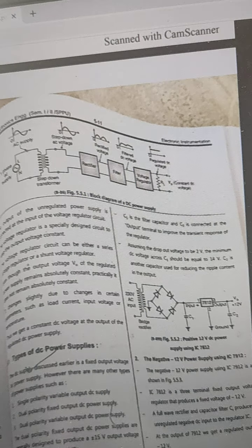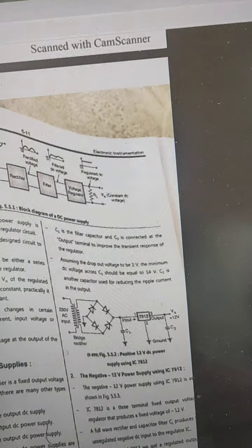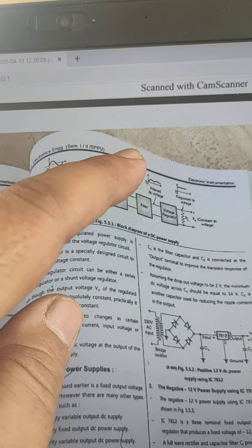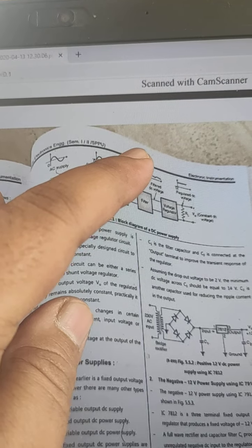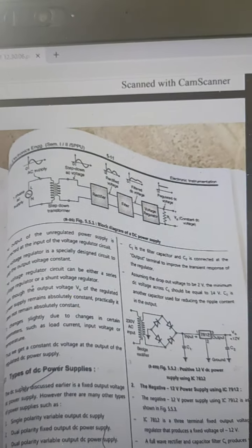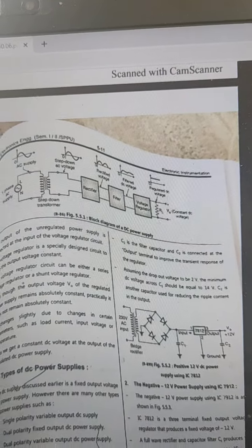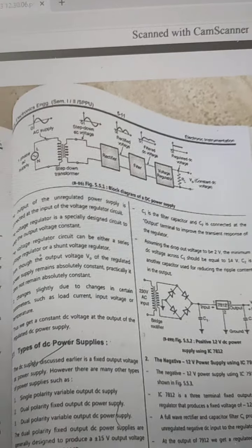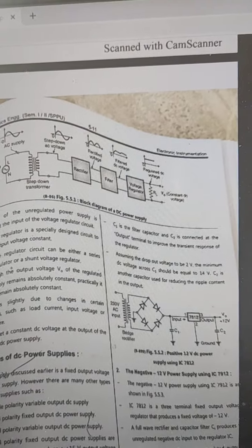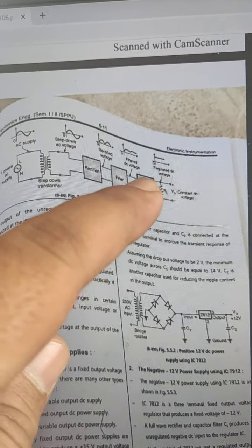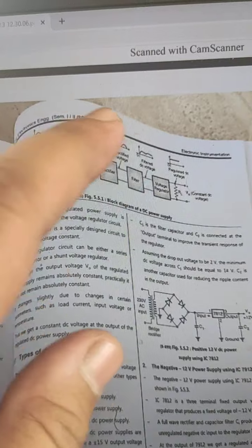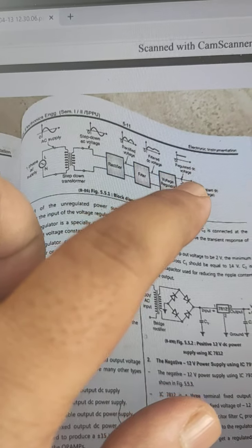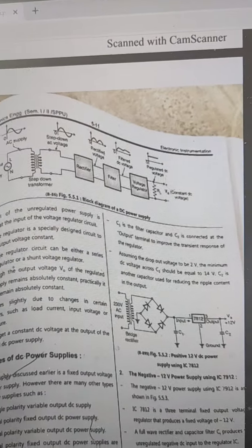As we are using a capacitor filter here, what happens is at each output of this rectifier, the capacitor charges for the positive half, discharges for the negative half, again charges for positive, again discharges. So we are getting an output like this, which we call the filtered DC output voltage. This is the complete filter output, but it is not constant, and as we want a DC supply, it should be a straight line. So we go for the next stage, the voltage regulator. The voltage regulator will make the voltage constant. Whatever voltage we are getting, it makes constant, and that we call a regulated DC voltage. That is the AC to DC power supply.